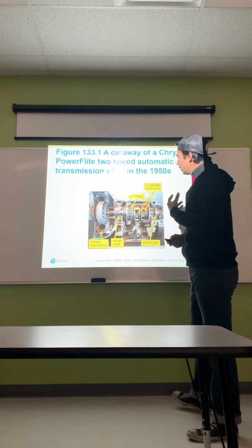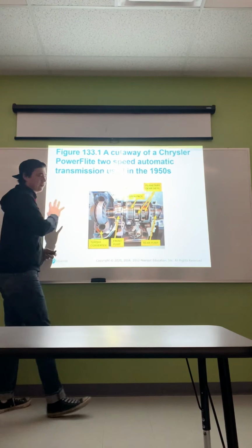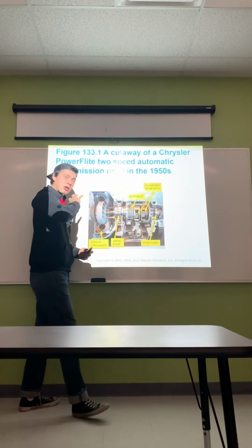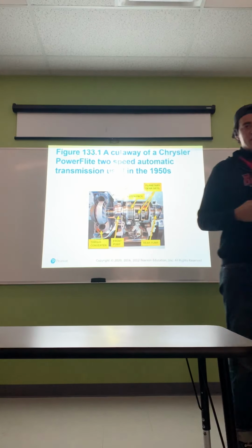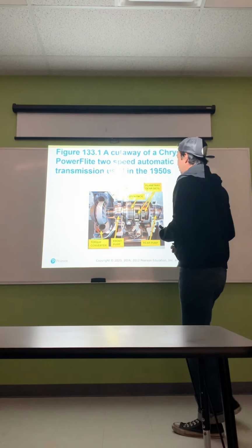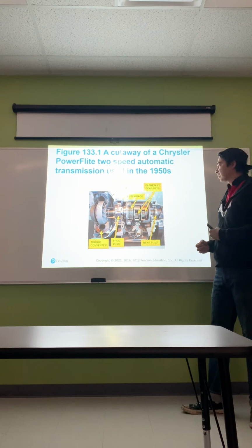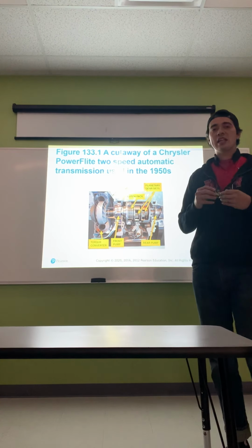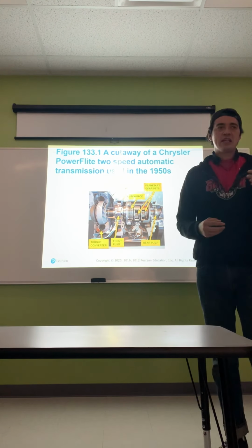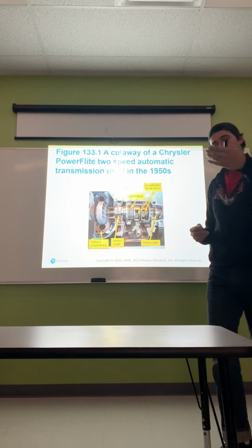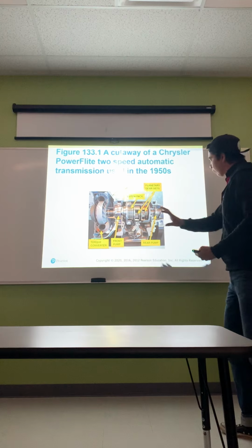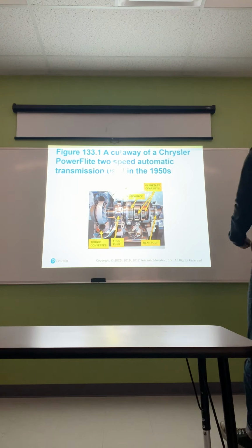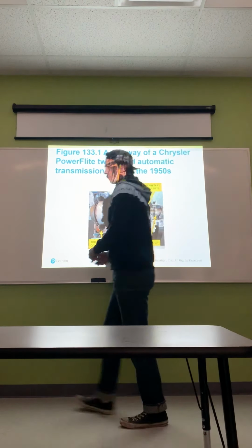Let's talk about the basic fundamentals. We're going to start off talking about the torque converter, and then you have the pump, which pumps the fluid through the transmission. We have a series of clutches that helps us engage into certain gears inside the transmission. There are gears inside, but it doesn't rely on those gears to give you a certain ratio and the transition of power through the input shaft, or say the torque converter, throughout the transmission. We're going to get more in depth with that throughout the module, but let's talk about the fundamentals of how a transmission functions.